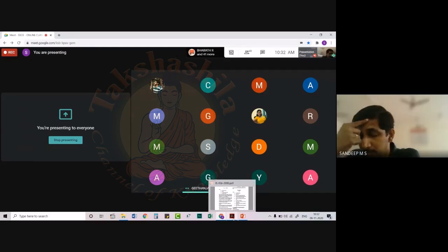First of all, we have to say, as the example which I have mentioned, if MU is 50 and MT is 75, we have to take 75 plus 50 and design reinforcement in the tension zone. In addition to this, we have to take the difference between MU and MT, that is 25, and for this 25 we have to provide some reinforcement in the compression zone also.